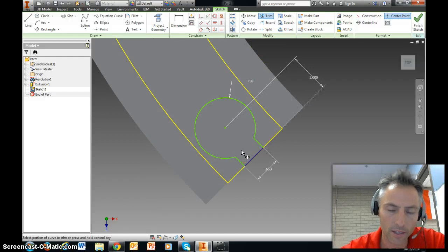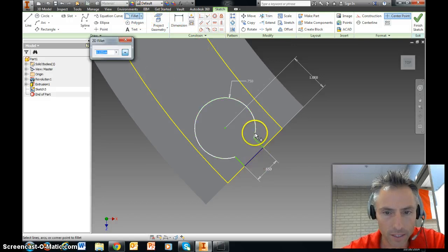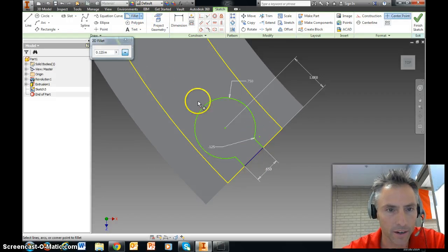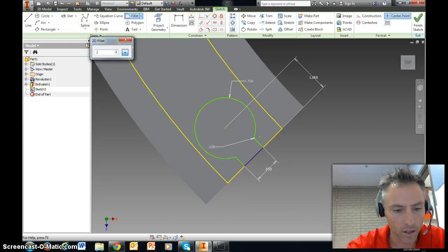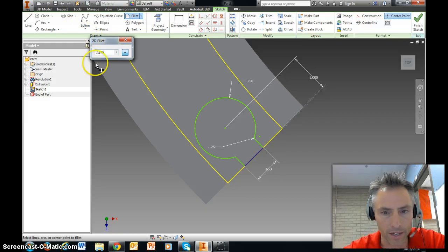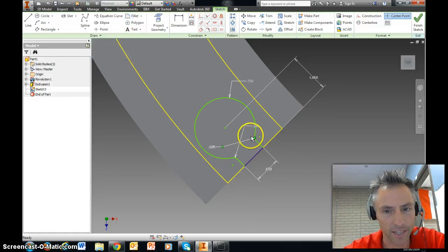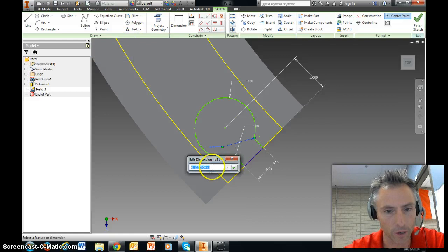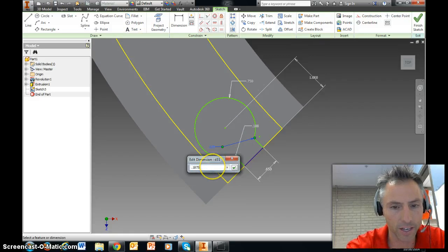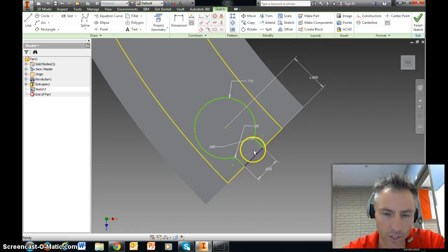and click that. And now we're going to go back to our fillet. And let's make sure we fillet that to there. And we can go ahead and put in 0.1875. Remember, that is the 3/16. So I'm going to go ahead and plug that in right there to there. I think it might be causing an error because I didn't originally have the 0.1875. Oh, there it is. It went. But to get that second one, or the one I did first, I'm going to have to go back to it and change it to 0.1875. That's our 3/16 dimension that we used.